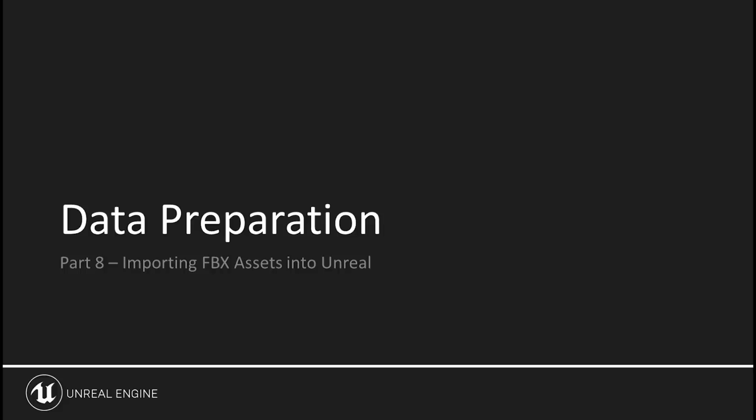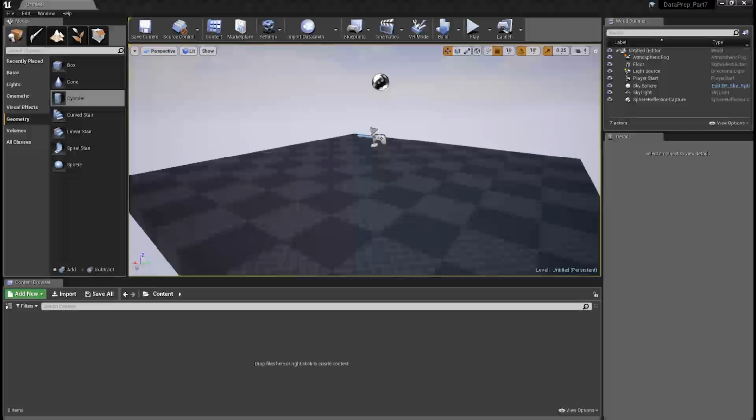Now that you've exported all your assets from the tool, importing them into Unreal is easy. Remember, Unreal is quite forgiving of poorly prepped data when importing. It'll import unoptimized 3D meshes no matter if they're set up using the same coordinate system and unit size or properly named assets for that matter. But if you follow this course and perform all the prep to your data as advised, the data will come in beautifully ready for creating your live walkthroughs.